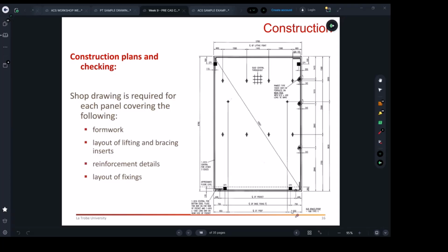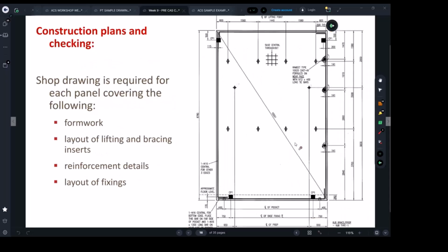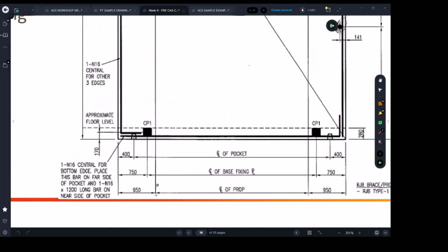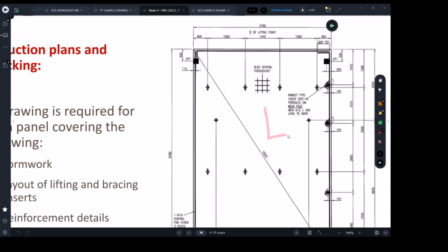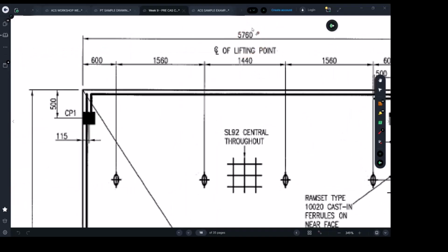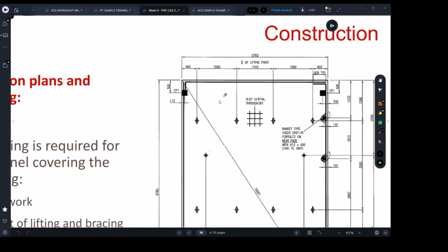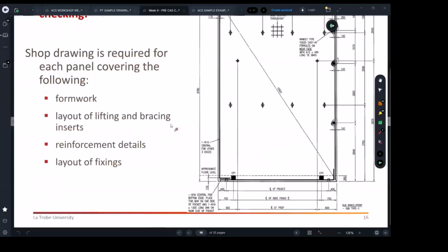And then you will share them with the architects to review, and you will share them with the engineer to review, who mostly are going to stamp them and say, yes, we checked them. But when the engineer checks them, the engineer will only check the steel and the thickness. The thickness will be documented somewhere as well. They will check whether they got the right steel, if they have a steel beam to be fixed here. So they will also check if the plate is here, right? But the engineers won't be checking the dimensions. The architect will be checking the dimensions. But on top of that, you will also need to oversee all those processes happening as a construction engineer.